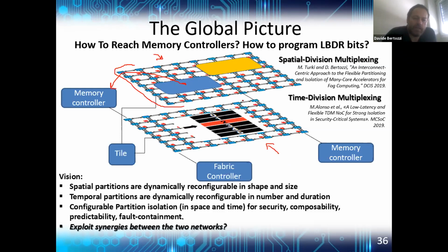And there is today an intensive research to come up with a time division multiplexing NoC that implements as few buffering resources as possible, because the Achilles heel of time division multiplexing for NoCs is the instantiation of large amounts of buffers. But there is promising ongoing research to build time division multiplexed NoCs inspired by the channel dependency graph, and that can minimize the amount of instantiated resources. So yes, true, you have a dual network on chip, but the second one is as lightweight as possible.